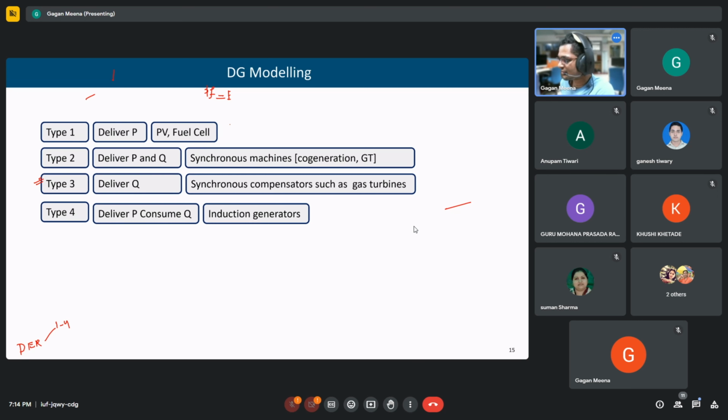Sir, but wind farms are using induction generators. Yes, then they use DFIG. There is no need of using capacitors to make the power factor unity, because these DFIGs have converters with them. They are interfaced to the grid with the help of these converters, so we can manipulate the firing pulses in such a way that they can operate close to unity. We can ensure the control in such a way. Even HVDC converter transmission lines also have reactive power compensators. Even the converters have such compensators if required.